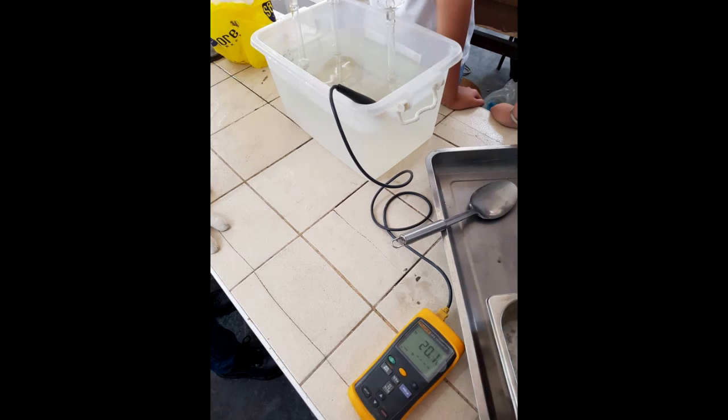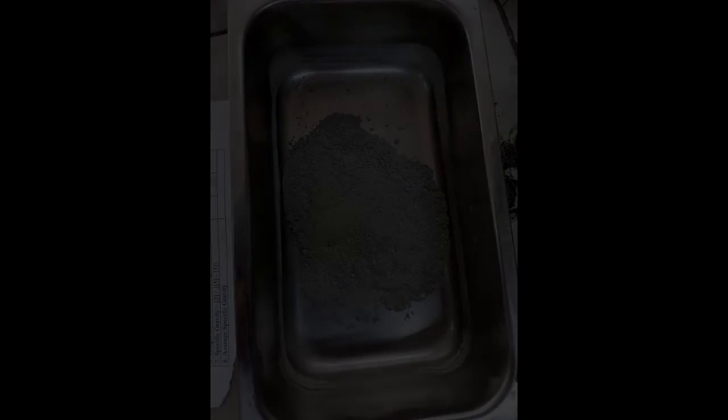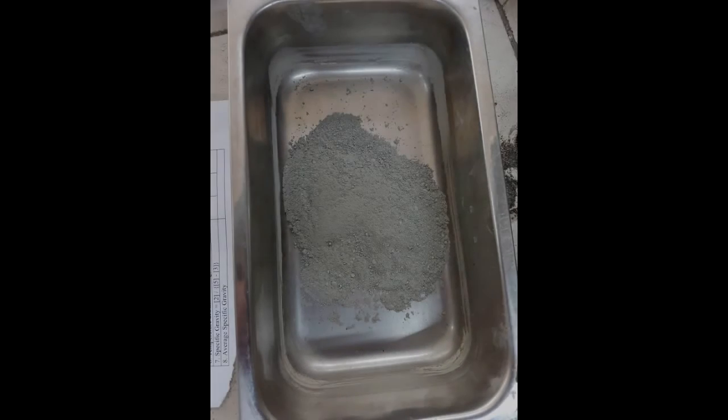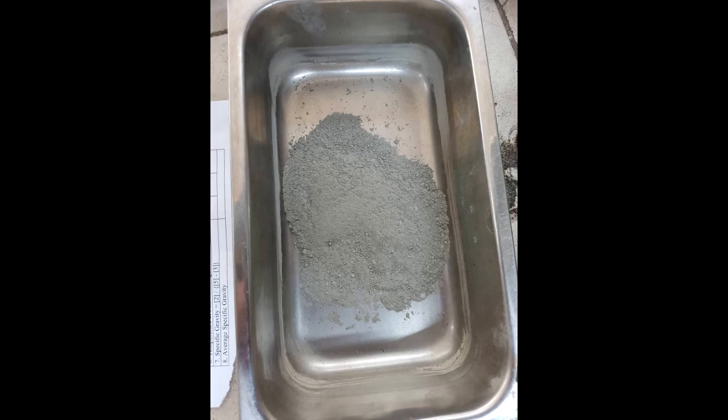Then, prepare an amount of cement of around 62.4 grams. Next, put the cement inside the flask containing the kerosene. Then place the flask with the cement and kerosene in the water and keep the temperature of the water at 20 degrees Celsius. Repeat the procedure until 3 similar readings are achieved. Lastly, remove the cement and kerosene from the flask. Clean the flask using a piece of cloth.